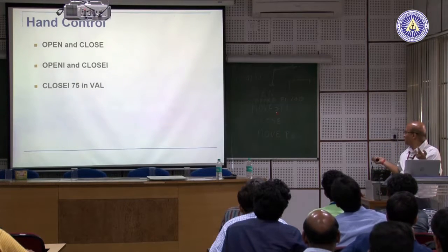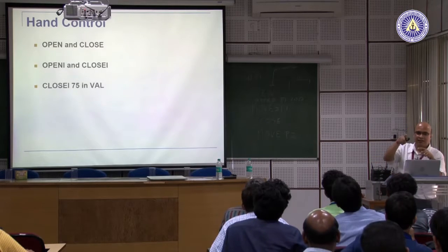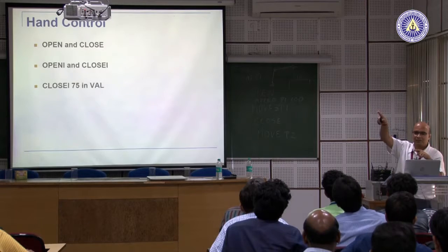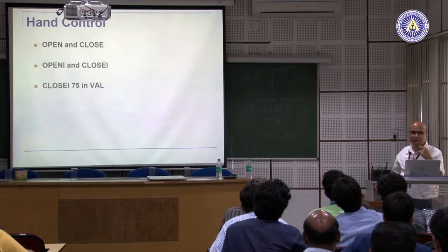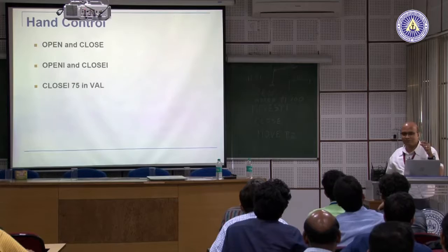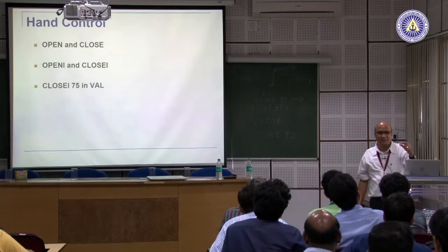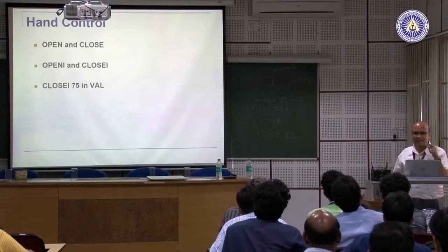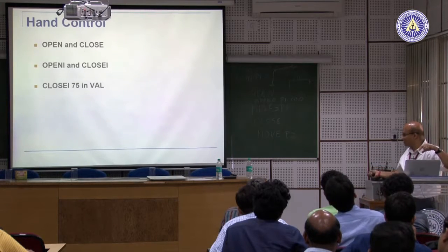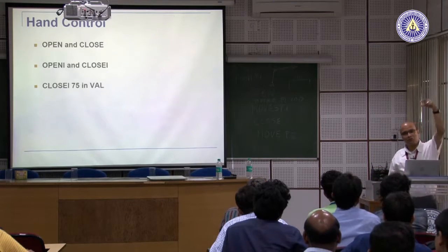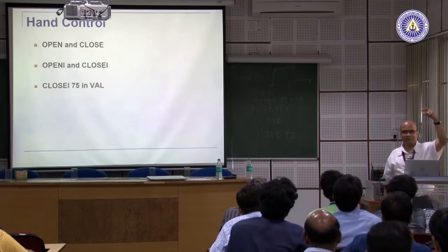Similarly, here it says move P1, it has come to P1, then it says close, it goes to the gripper controller and says close, and as far as the program is concerned, it has closed, and then it goes to the next one, says move. When it is closing or opening, it will take some time, it is not instantaneous, right. So, when it says close and the gripper is closing, it goes to the next line and says move, it has already moved without closing.